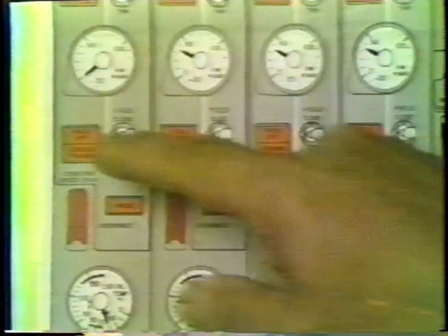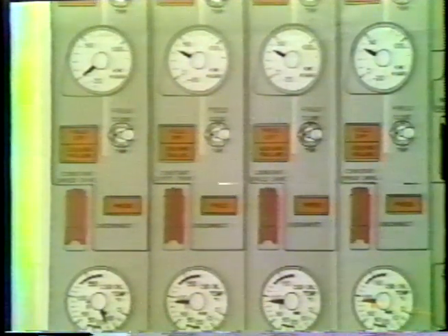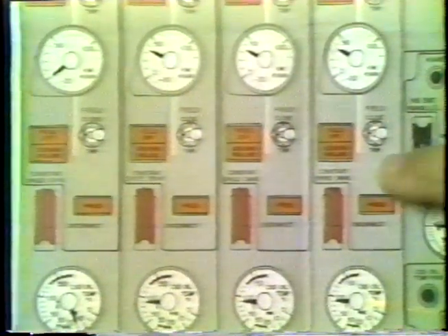Field switches. Field switches are off-on switches for the generator. When the switch is tripped, if the generator breaker is also closed, it will trip it. When the switch is closed, it makes that generator available to operate an electrical load. Of course, when the engine is shut down, the field will stay closed. However, the generator is not available unless the engine is operating at idle or higher RPM.